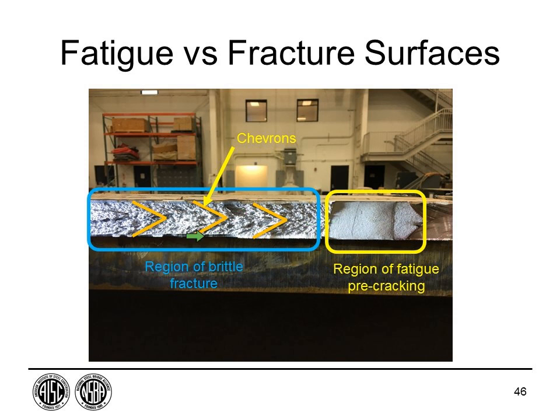There's another characteristic on the surface, and if you look kind of close with the shading, you see what are called, we've highlighted them here with these arrows, chevrons. And they actually point back, if you trace them, to where the fracture initiated. Now these are wonderful because for someone like me who goes out and looks at a failure, I can point back to where it initiated and people think I'm smart, but really the crack points back to where it initiated, so I shouldn't take credit for that. But they're very characteristic of sudden brittle fracture, this pattern of chevrons, and by holding a flashlight at certain angles you can reveal those.